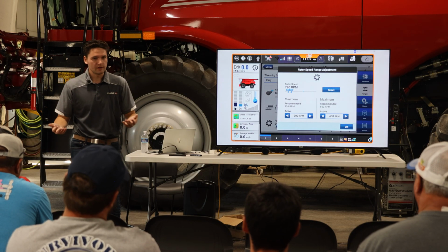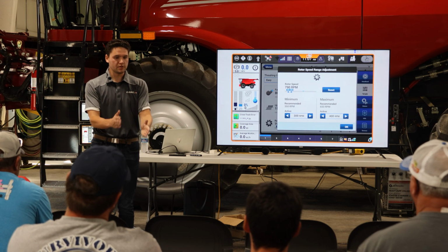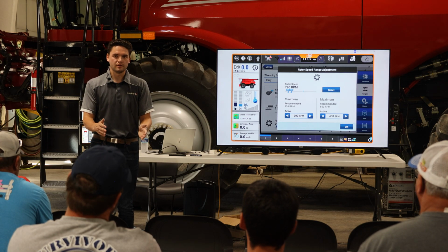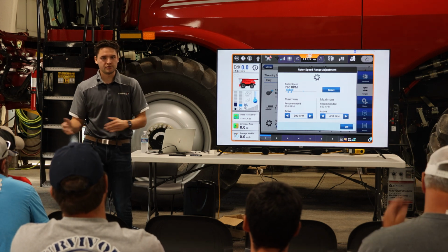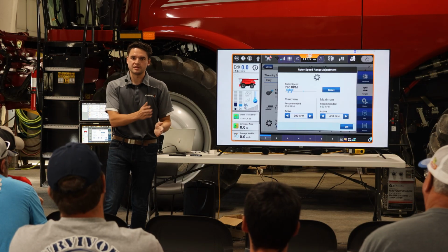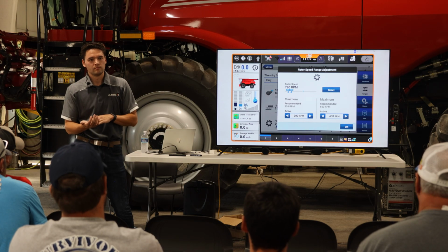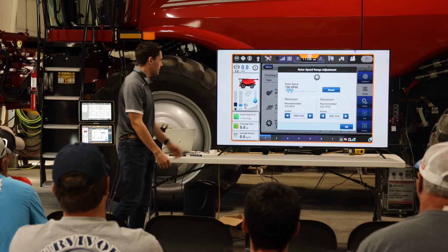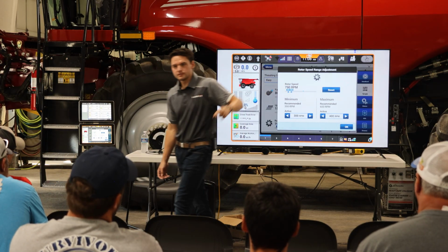And at the same time, why would I jump 100 RPM and limit it to only being able to adjust 100, when if I do 50, it now can jump between 200, right? Why would I limit the machine if I don't have to? So I do small increments to bring it down, because I don't want to neck it too much, because then it limits the amount of set points it can do for the different harvesting conditions. Does that make sense?